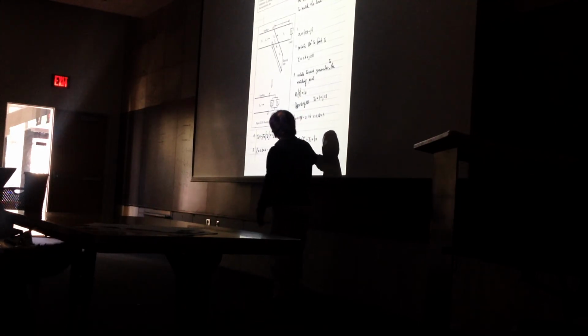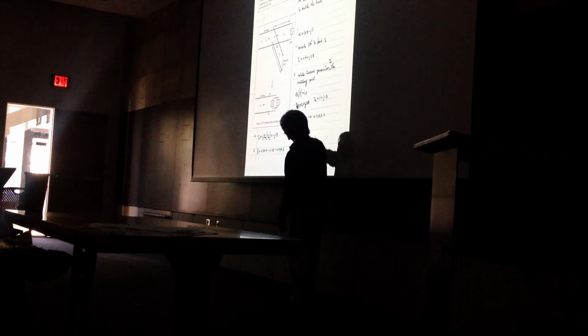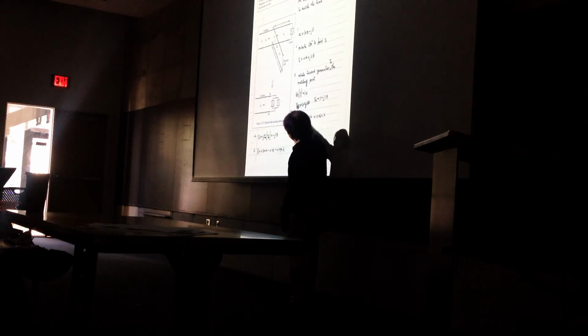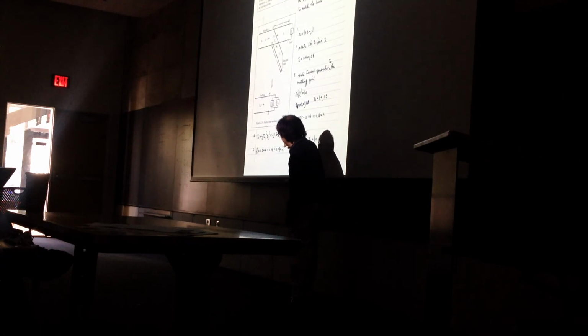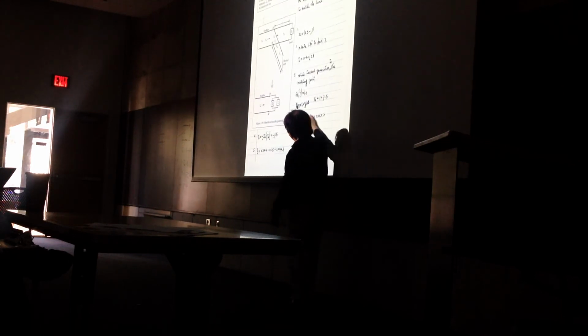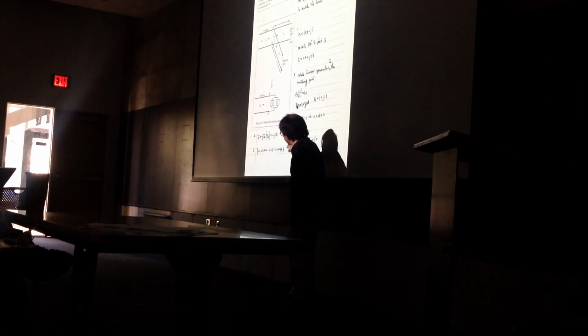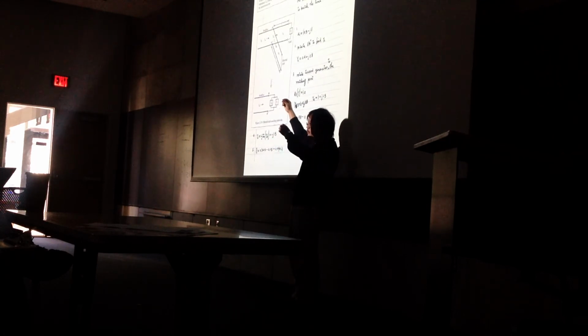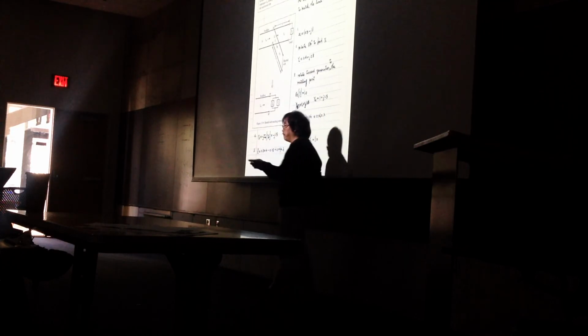Adding together, the total will be your load admittance plus your matching admittance, and the imaginary parts will cancel each other out. So the total admittance now will become 1. On the Smith chart, it moved from the point to the center.